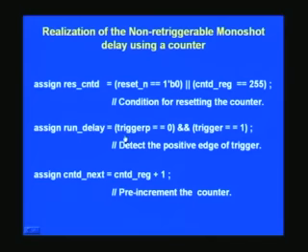What you can do is have another signal which will store the previous value. So every time the clock strikes, you can push the current value into another flip flop and then store it and use that one in the next clock. So you will know what was available in the previous clock. By ANDing these, say for example the previous value is 0 and the present value is 1, naturally you can sense that it has a rising edge as far as this signal is concerned.